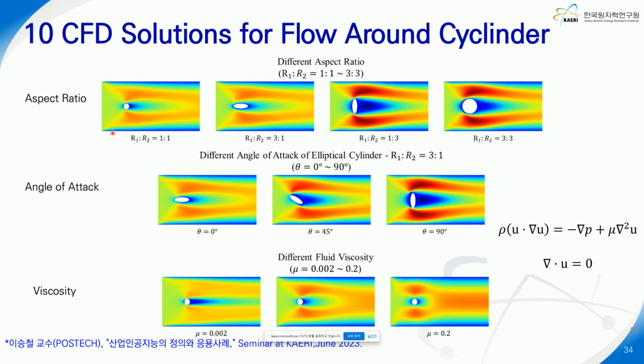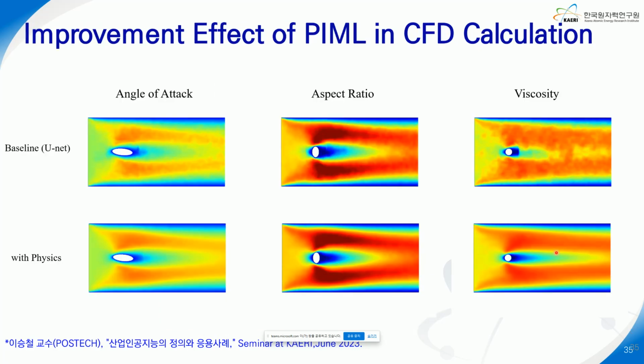4 CFD solutions were generated with different aspect ratios of the cylinder, 3 with different angles of attack, and 3 different viscosities. These 2 are the governing equations of the flow which will be used for the residual evaluation through differentiation.